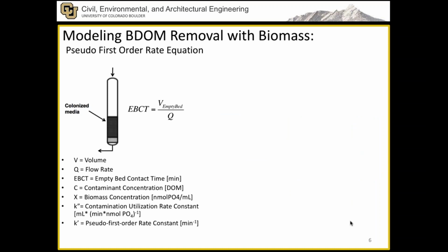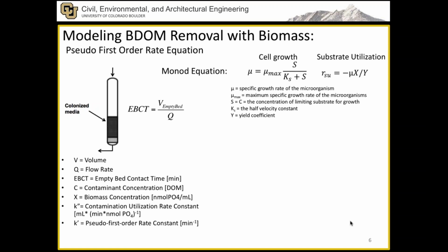This work also looked at modeling biodegradable dissolved organic matter removal within the biofilter. So here you see a schematic of a downflow biofilter. Empty bed contact time is the volume of the empty bed of the filter divided by the flow rate. And we used Monod equations. We combined the cell growth as well as substrate utilization to derive the change of concentration over the time it spends in the biofilter.